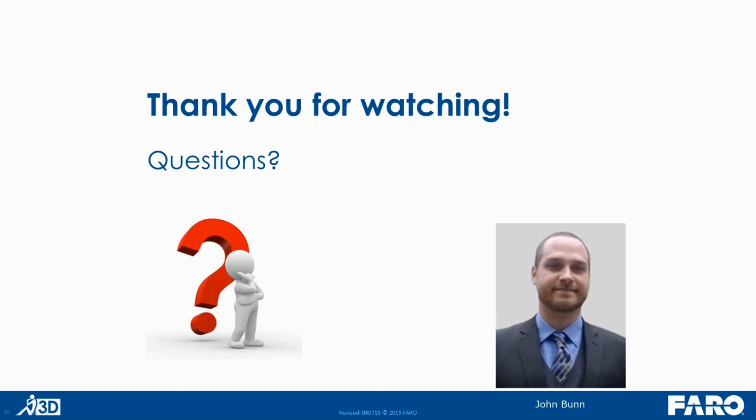The other thing, and more importantly, is the scan navigation. Let's say you have 150 scans and 2 billion points. You've got them all on your screen. The visual quality is down a little bit, and the speed's down a little bit. When you jump into that scan navigation mode, you are removing any other data that is not line of sight to the scanner from that position.